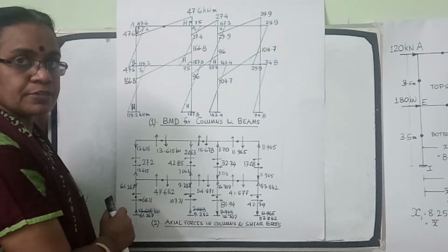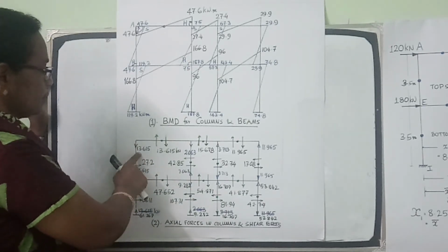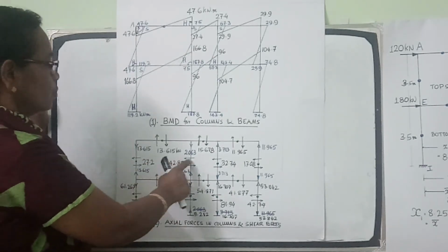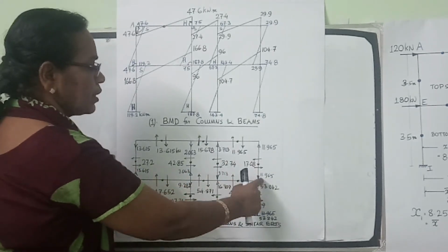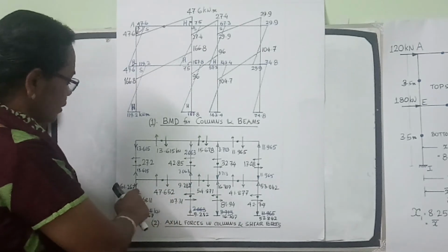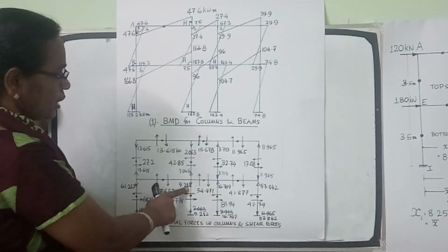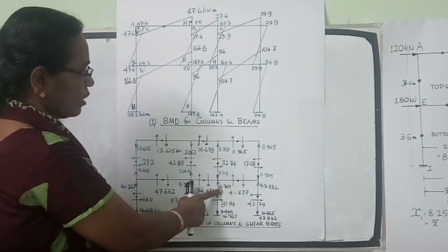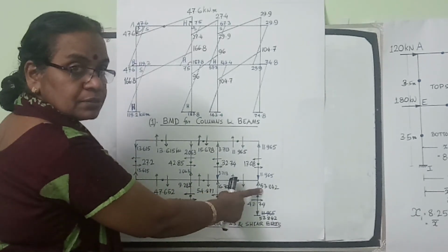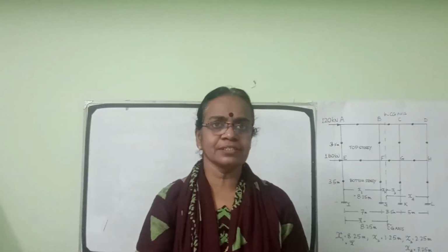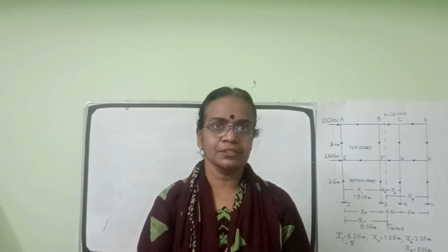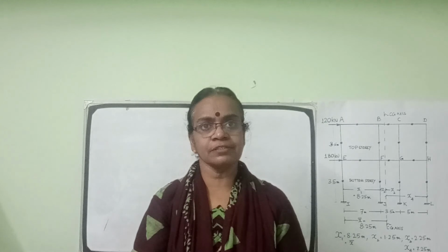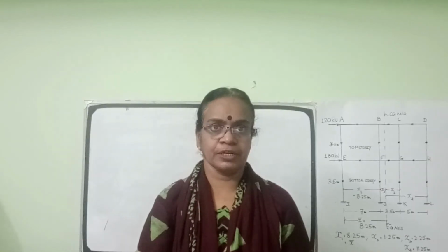Next, coming to the axial forces in columns. The axial force in the top story columns is 13.615 tension, 2.063 tension in these two columns, 3.713 compression, 11.965 compression. Similarly, for the bottom story, 61.267 tension, 9.282 tension, 16.7 compression, 53.84 compression. Thus, we have completed the analysis of multi-storied building frames subjected to lateral loads by the cantilever method, and all the results obtained from steps 1 to 6 have been represented graphically in two figures. Thank you.